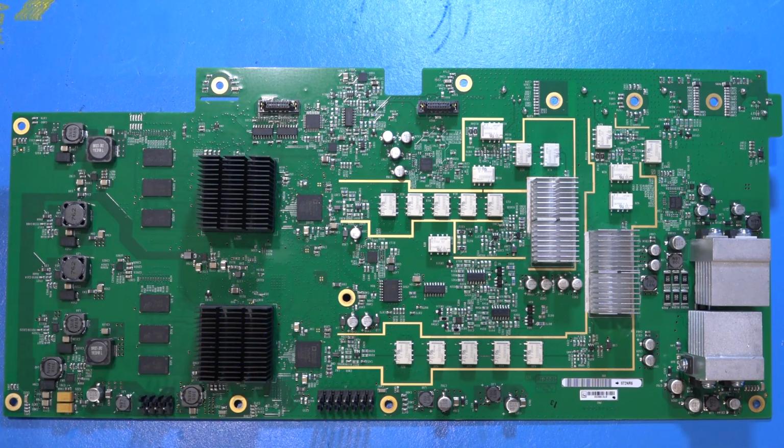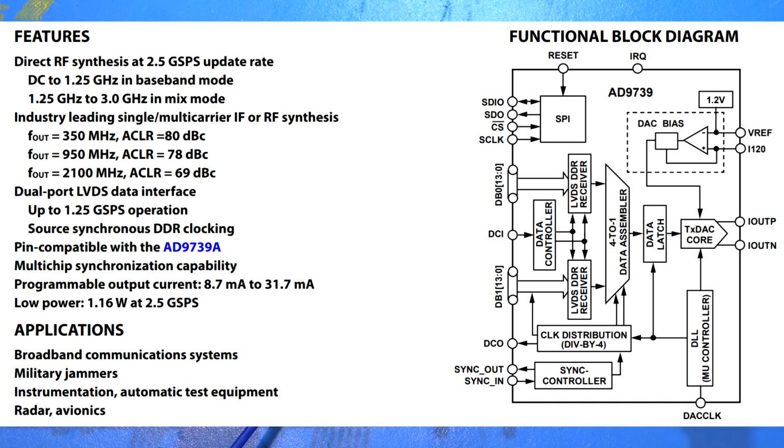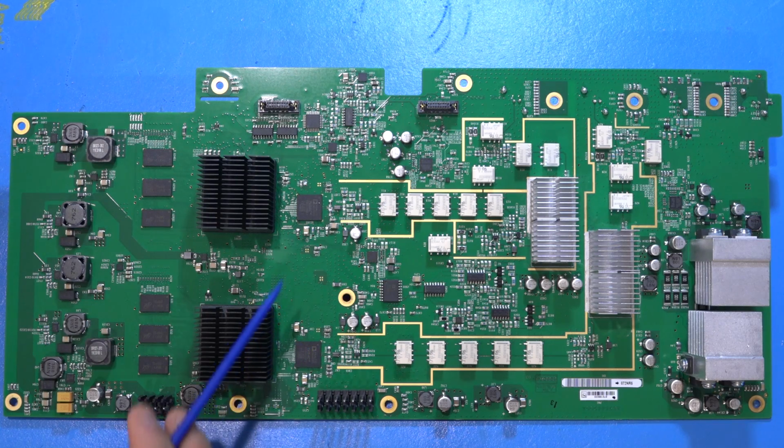These two DACs are completely independent analog devices, AD9739 TX DACs, and these are 14-bit 12.5 gigasample per second RF digital to analog converters. The reason they are called RF digital to analog converters is because everything in the back end can be essentially digital up until the output, and you can directly connect the output of these TX DACs to antennas if you wanted and produce a radio and do transmit and do modulation and do data.